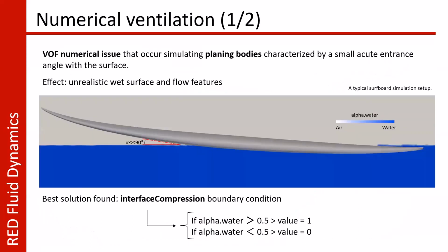Talking specifically of the numerical ventilation, this is an issue related to the VOF technique that occurs when simulating planing bodies characterized by small angles between the planing surface and the interface between the fluids, such as in this case.